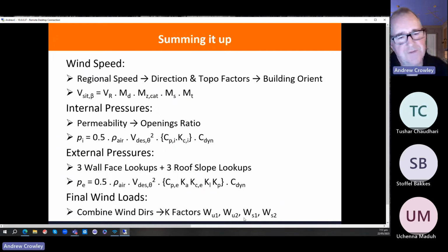So you're designing for strength, but you also check for serviceability, usually deflection. For lightweight buildings, actually, our lightweight portal frames, the deflection under wind load can be the critical factor. So the structure could take lots and lots of load above the design load, but the deflection is too much.